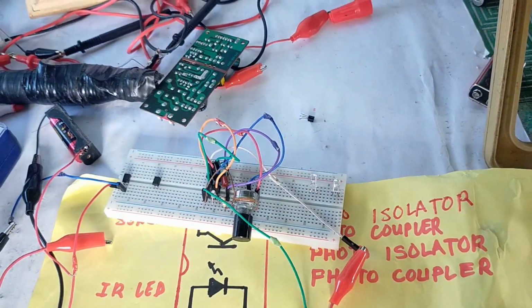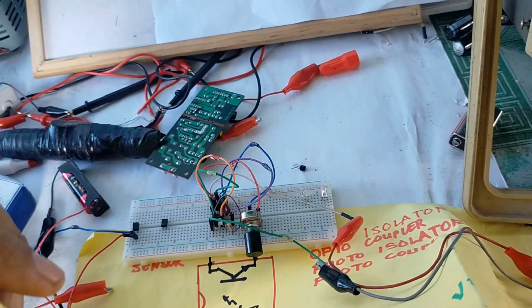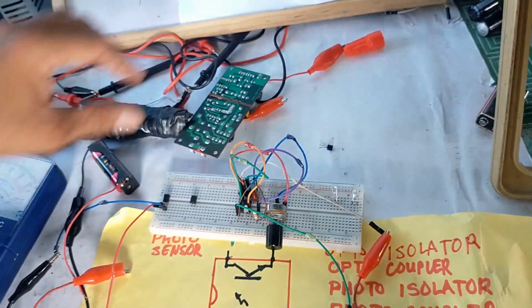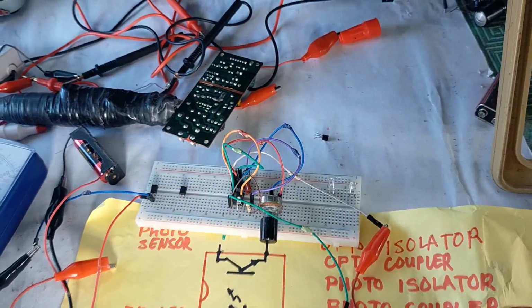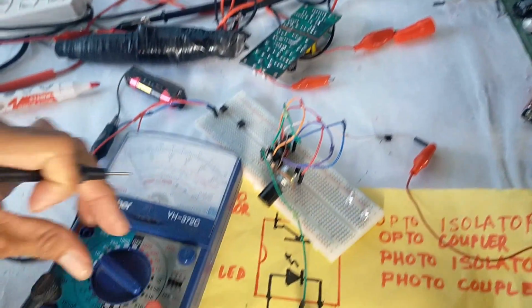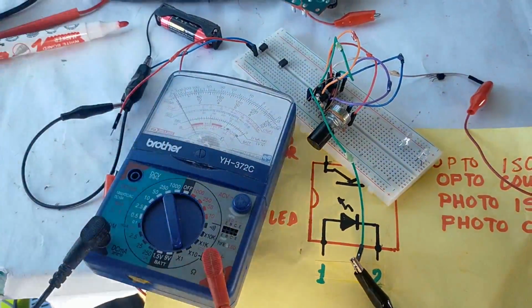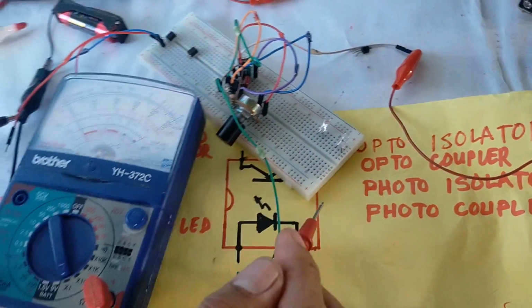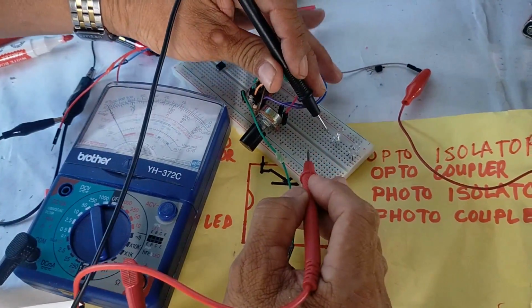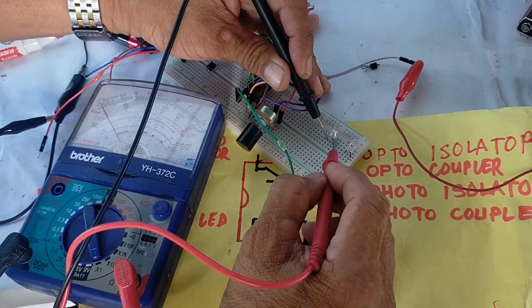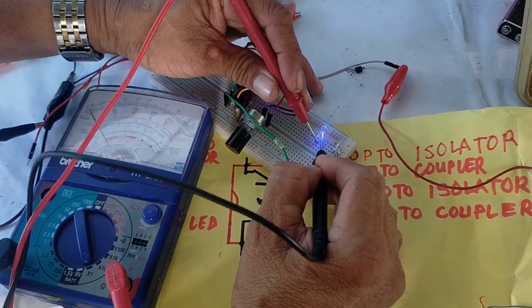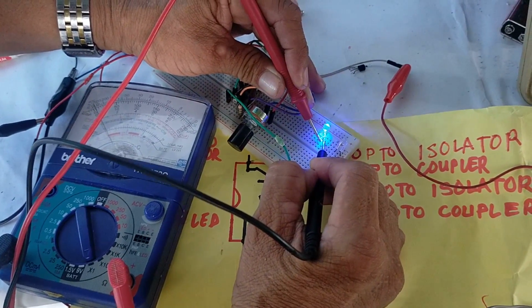Voltage, okay, we will use again the times 1 ohm range to measure the two types of light emitting diodes here. So this light emitting diode, once it is supplied with voltage from the ohmmeter, it gives light.